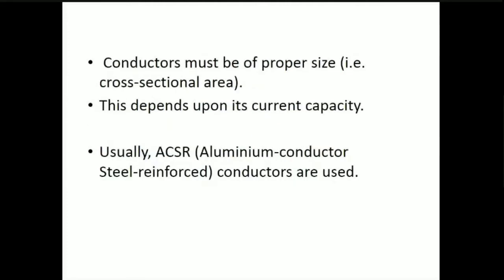Conductors must be of proper size, that is cross-sectional area. The cross-sectional area of a conductor depends upon its current carrying capacity. Usually ACSR conductors are used. ACSR means aluminum conductor, steel reinforced.